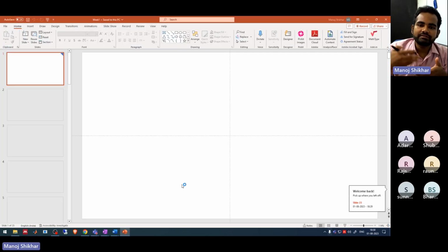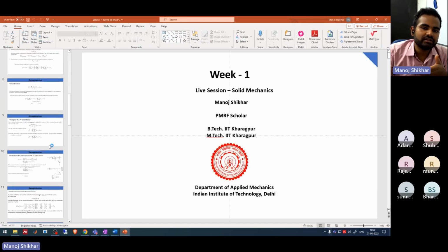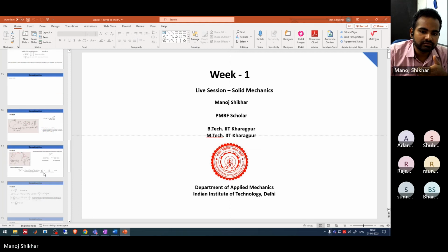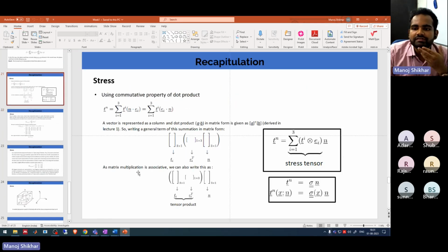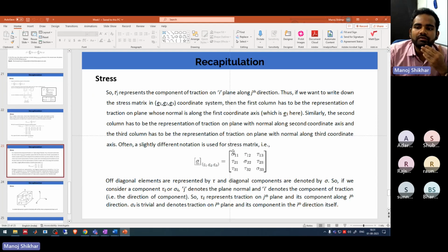And the components which we have in this stress tensor, in this stress matrix, these are formed using different components of tractions in 3 different directions. So those directions should be independent. This has been covered in the class also. So the units are the same actually for traction and stress matrix. The units are actually Pascal only. By mistake I told that differently.